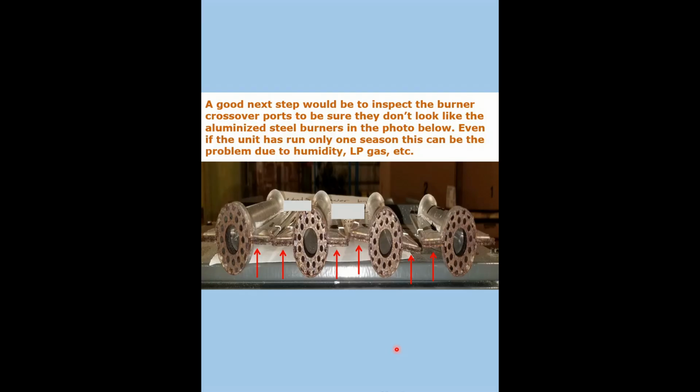Pull a burner out, the one closest to the igniter, and see if the crossover ports on that are all gummed up like this one is. It might save yourself a lot of trouble.